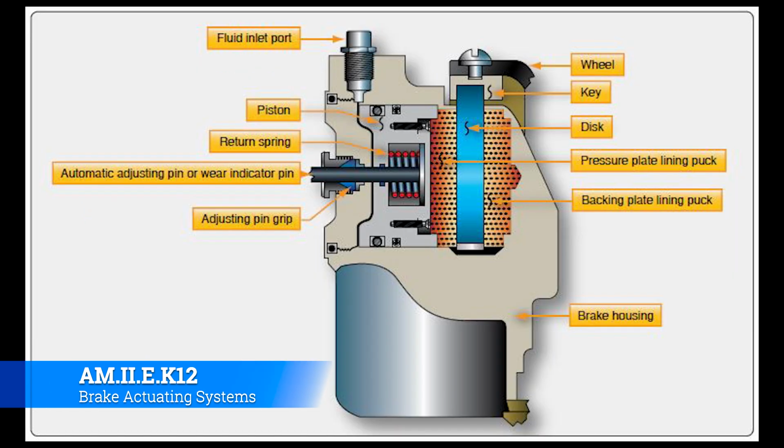Okay, here's a cross section of what that would look like. What I want you to focus on is the return spring, because that's a part that often gets overlooked in brake construction. A lot of people will focus on the hydraulics and the calipers, but they forget that the return spring is extremely important in order to get the caliper, the puck, the lining, whatever your preferred nomenclature, to pull back so the brakes can be either on or off. That is a critical component of the whole floating disc brake construct.